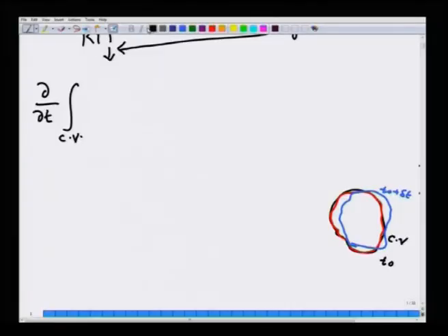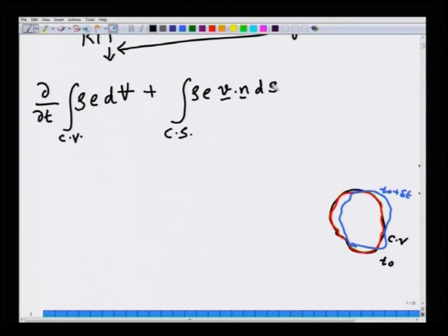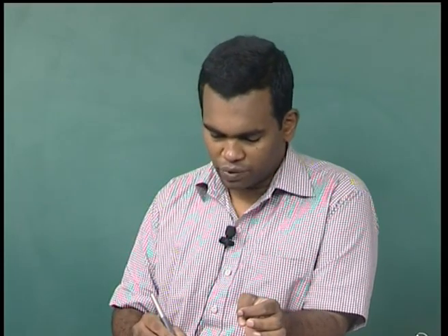That is given by the Reynolds transport theorem in terms of variables pertaining to the control volume as follows: integral of rho e dV plus integral over the control surface of rho e v dot n dA, is equal to Q dot minus W dot. In order to understand the various contributions to the work interactions between the control volume and the surroundings, we imagined in the last lecture